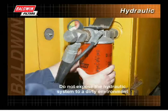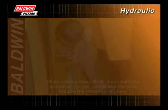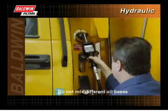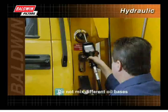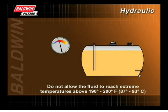Do not expose the hydraulic system to a dirty environment. Keep the fluid level up in the hydraulic reservoir. When adding clean fluid, make sure the container, funnel, pump, and the area around the reservoir is clean. Do not mix different oil bases. Make sure the hydraulic fluid being added is compatible with the hydraulic fluid currently in the system. Do not allow the fluid to reach extreme temperatures above 190 to 200 degrees Fahrenheit.